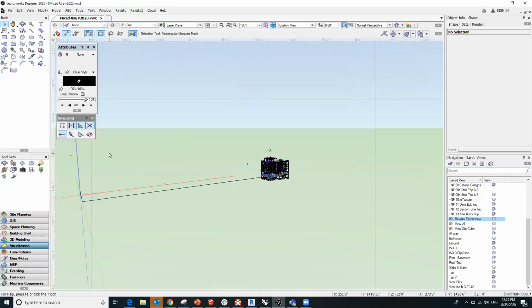So first, you'll have the internal origin, and that can be shifted around, I believe. However, moving that point can create some problems in the project. So if I move the internal origin and I have my sheets set up or views, et cetera, the model will move. However, some other aspects of the project might become disjoined. So there is actually another way that's handled in Vectorworks. I can position this model to read a different point as opposed to the internal origin, and then export to the correct location in Revizto.